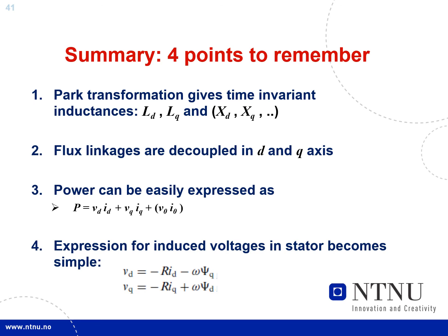So to sum up, the last slides on complete models were more for your information, I would say. But these four points that are listed, I think it's very relevant to remember: the Park transformation gives time invariant and decoupled inductances.